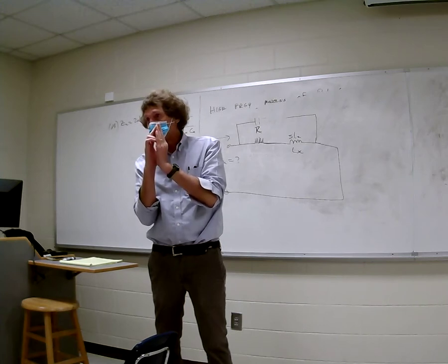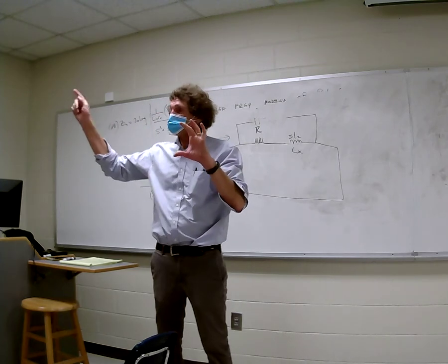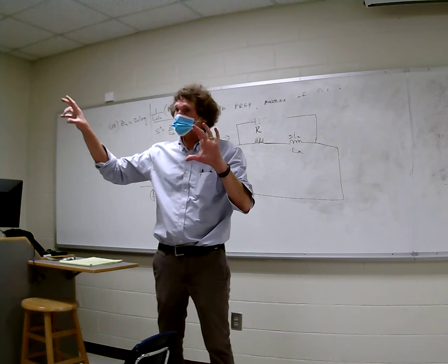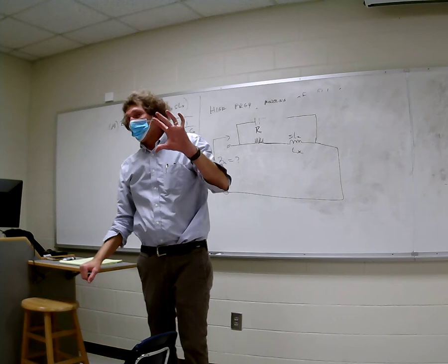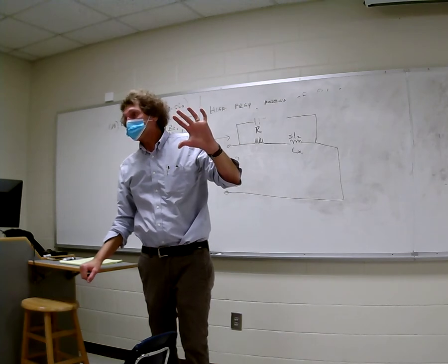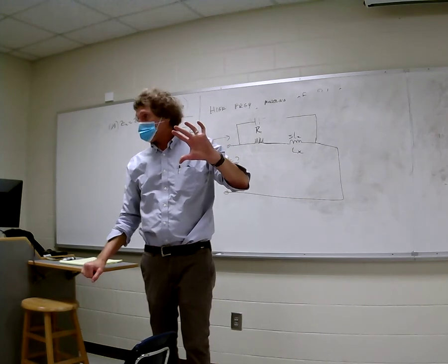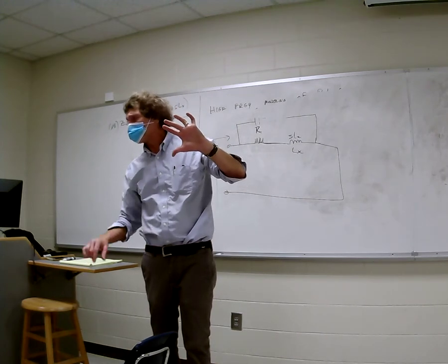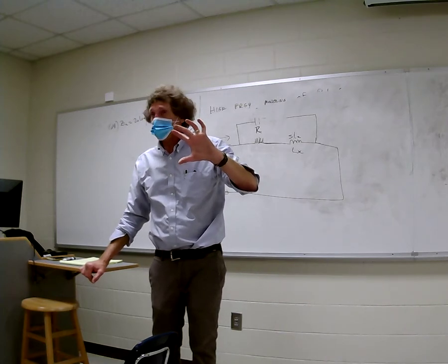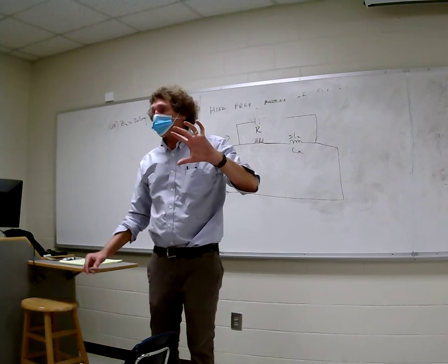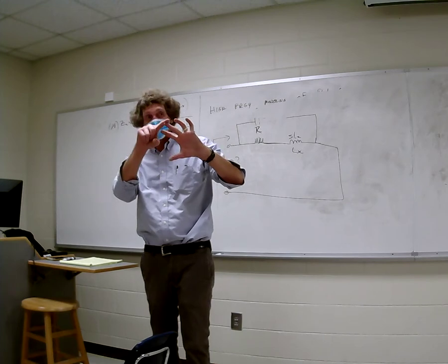They go boom. So, what they'll do is use large electrolytics after they come out typically of a full wave bridge rectifier where you get a DC voltage with a ripple. You all with me on that one? Those capacitors can charge and discharge in the current going the same way all day long. I mean, it's basically, they will allow, I should say voltage, they'll allow the polarity of the voltage to be the same, even though it varies in magnitude, it's not a problem. No problem.